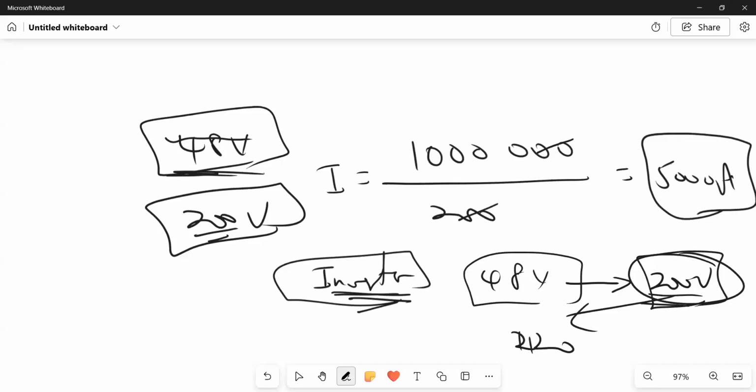So yes, as I said, these large installations have the electronics to deal with it. They convert the DC current from the solar panels to AC, then step it up to 66,000 volts or whatever else, transmit it, then step it down back to 220 or 110, and then use it. That is why we use AC current to transmit power to your homes.